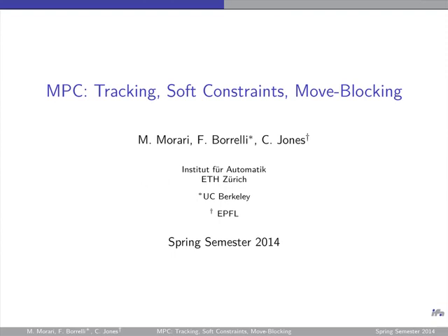So you greatly simplify the problem if you don't have those hard constraints. But you still want to have constraints on your states and outputs. But you can do soft constraints, and that preserves the simplicity, but gives you some bounding of the control action. So that's something that's very common, has been used for lots of years. And there's a way of doing it well and a way of doing it not so well, and that we'll discuss. And the final couple slides are going to be just to simplify the optimization problem that you have to solve online. Okay, so those are the things I want to discuss now.